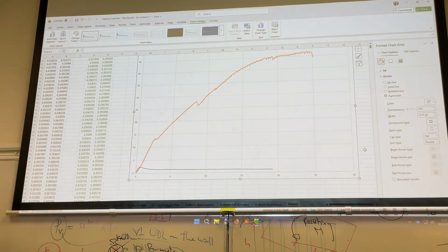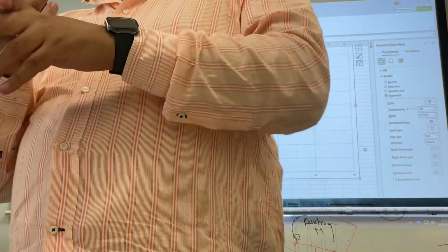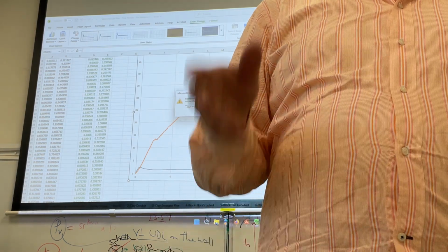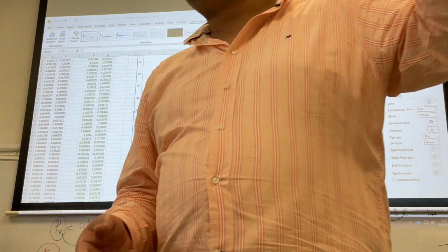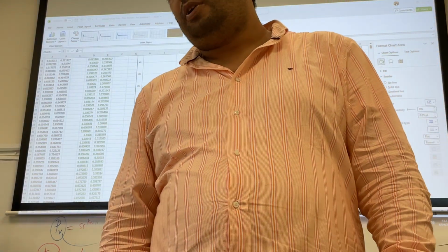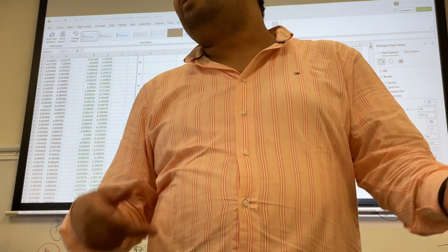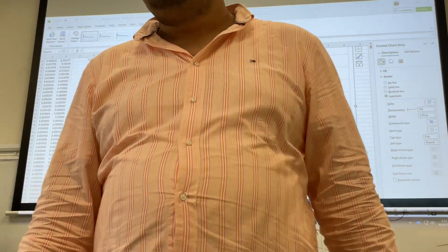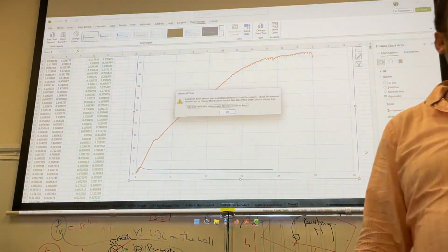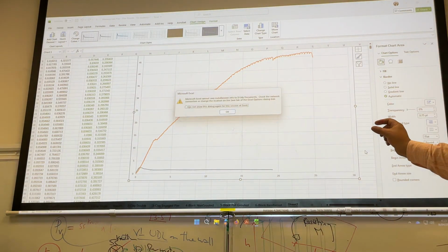You reckon all 6, or could we just keep all clay together and all hollow block? Whatever, but it's better to put all of them together. Well, you can compare each two, like for example, you have 3 the same: grouted, ungrouted, and reinforced. So you can put them together. But also a general comparison will be good, because all of them have the same height, same boundary condition, and same setup. So you can still compare them. In research, you can compare even if one is too weak, but this also shows the advantage of the strong one. I know the graph looks weird, but it's okay, because this one is only 2 kilonewton, the other one is 45, so it is 20 times bigger than the first one.